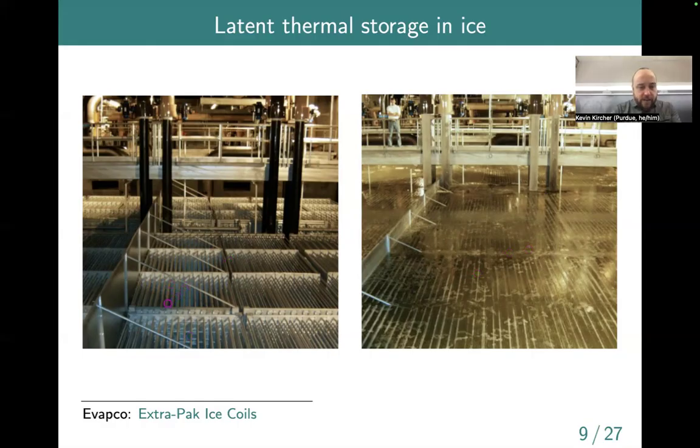And so all of these plates here, it's a little hard to see, but I think that they are plates of a heat exchanger. So they'd be very cold, basically, because they're in contact with a refrigerant that's below the freezing point of water that's circulating through these. So when you want to store cooling, I guess you would run very cold refrigerant through these. It would freeze. And the reason that the water level is higher here than it is over here is that water expands when it freezes, right?